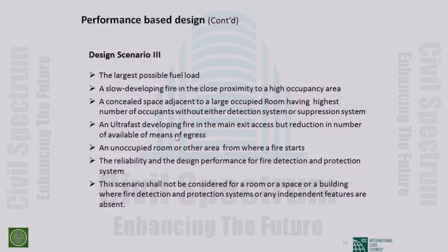It varies, but the pressure variation is about 0.5 psi. So with this deflagration a fire can move faster than we move. So assuming this, and assuming your egress system, you have to design your building and your occupancies.